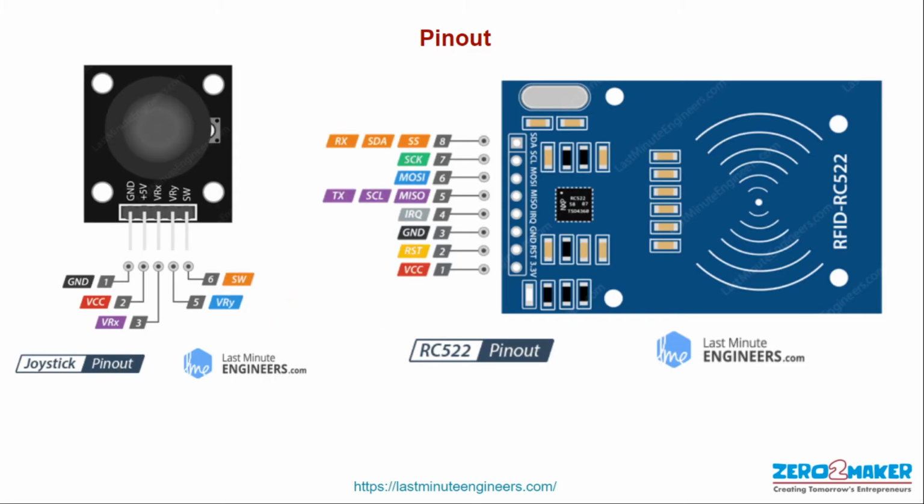Let's go further. We have one more sensor which is the joystick. The joystick will be majorly used for servos, like controlling the servo or some movement. Here the joystick has SW, which is the switch present on the top of the joystick. Then we have VRY and VRX. VRY and VRX are basically the direction of that particular joystick, which is formed with the help of a potentiometer. That gives you a directional outcome, and those 3 pins will go to Arduino.